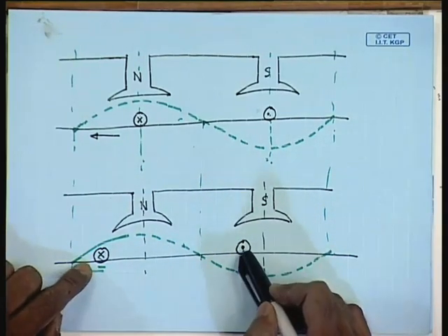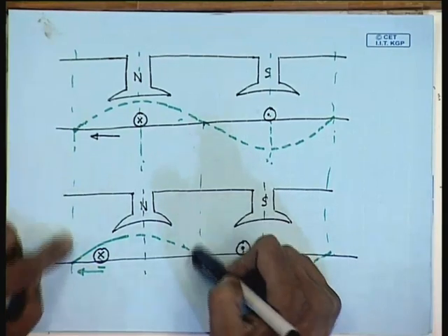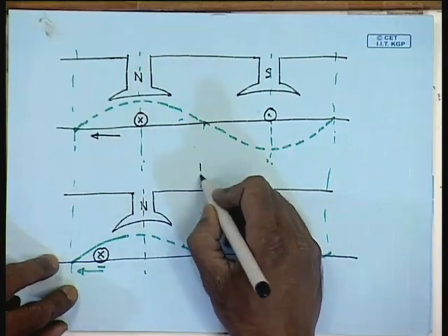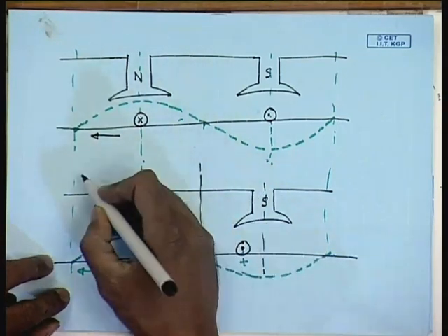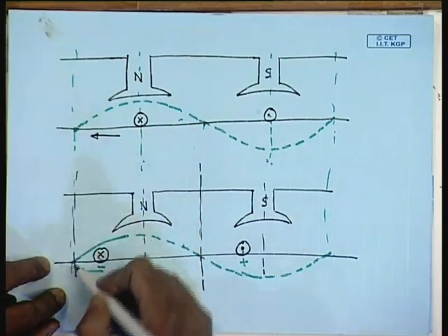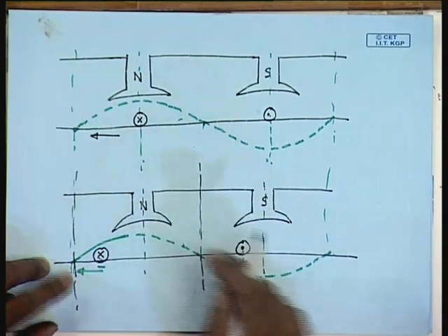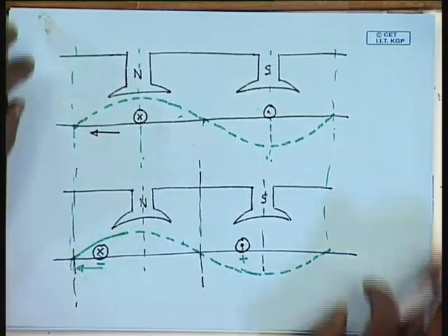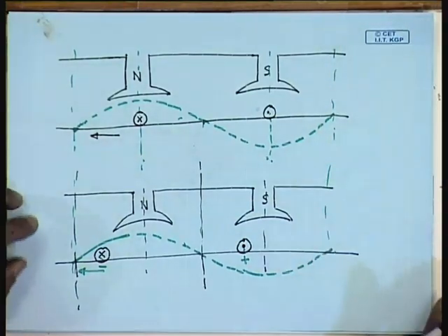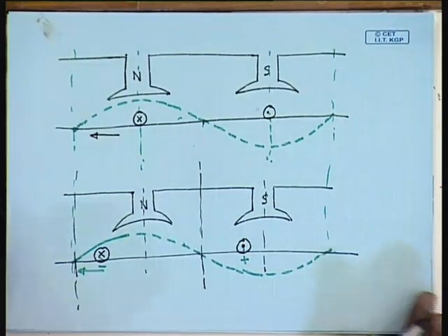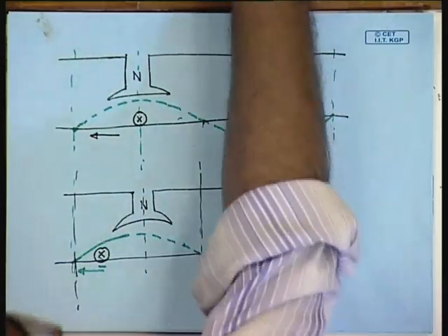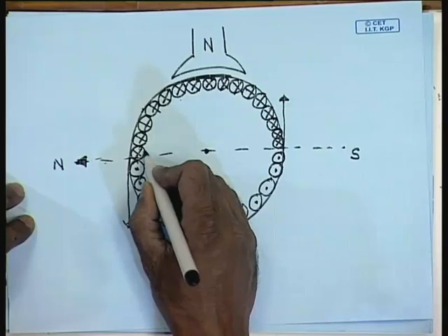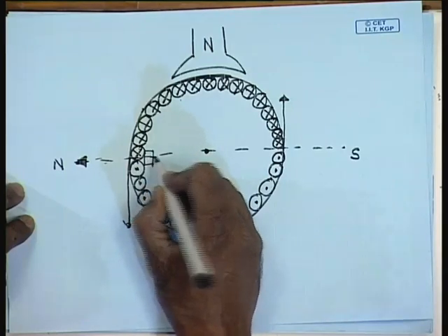That is, the coil sides should be at what we call the interpolar region, which is the middle position between two fluxes. The brush must connect to those coils which are at the interpolar region. That is why it is sometimes said that the brushes in a DC machine are placed at the interpolar position.